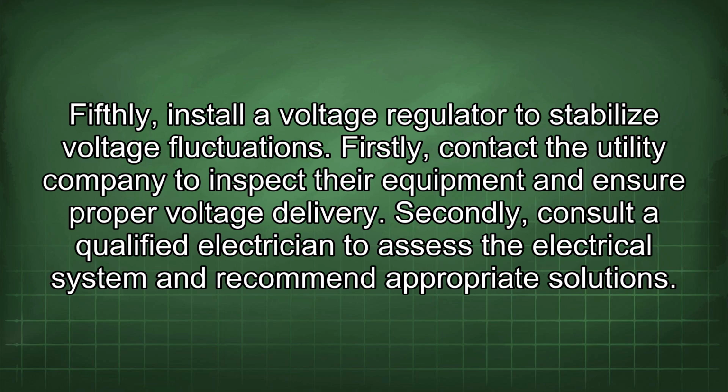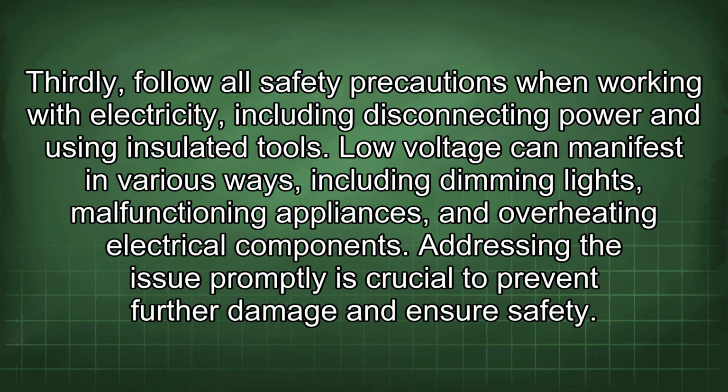Firstly, contact the utility company to inspect their equipment and ensure proper voltage delivery. Secondly, consult a qualified electrician to assess the electrical system and recommend appropriate solutions. Thirdly, follow all safety precautions when working with electricity, including disconnecting power and using insulated tools.